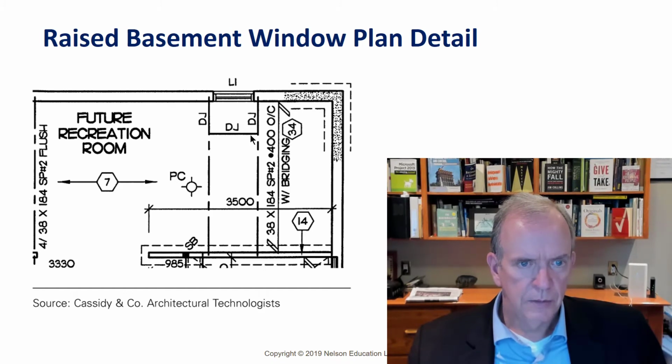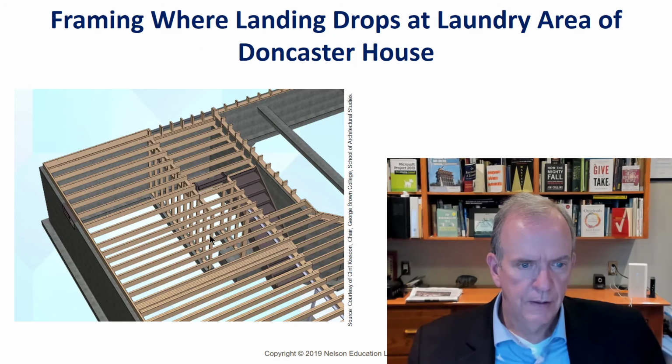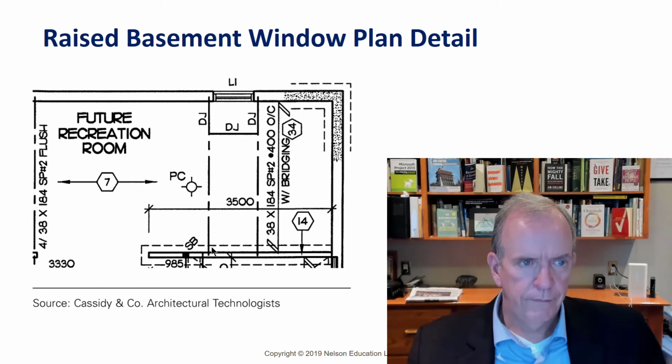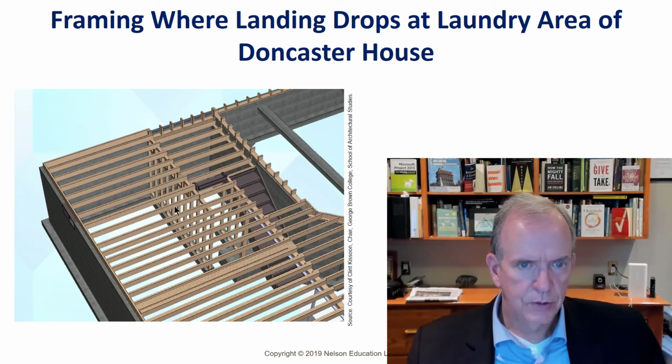And we can see here the double joist go around. We can see here, this is a load-bearing wall that's placed underneath a strip footing that goes around there. That dashed line represents a footing that this wall will rest on, which is this wall right here, underneath here. Good to visualize when you look at a drawing what you think this is going to look like. And the more you do it, and with the more experience you get, the easier it comes.